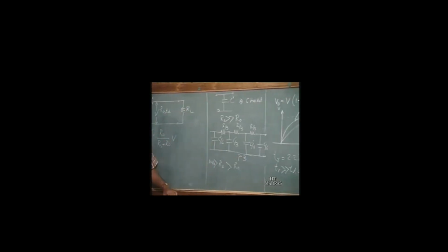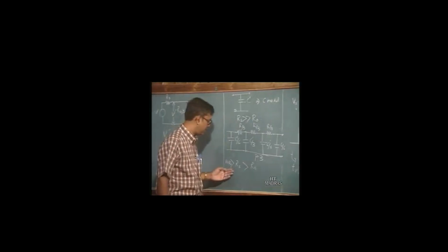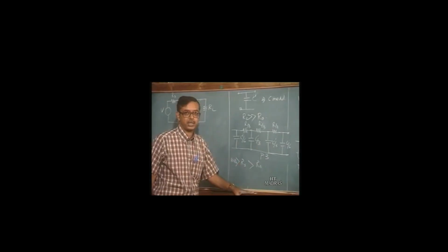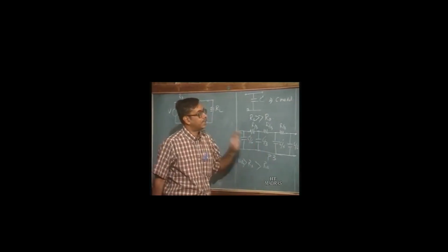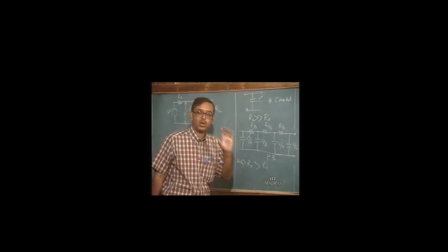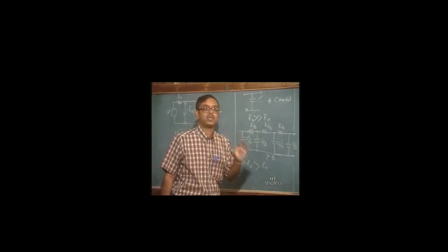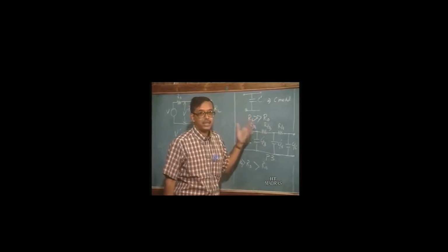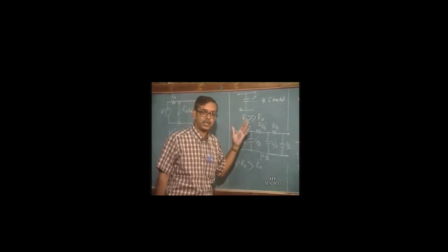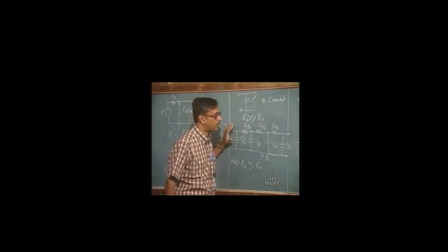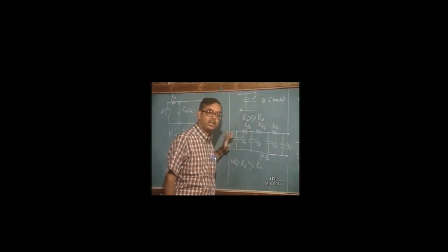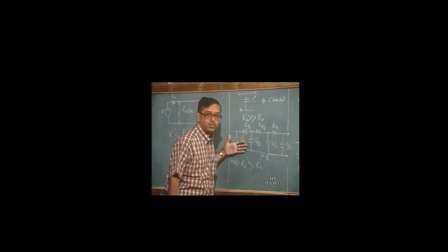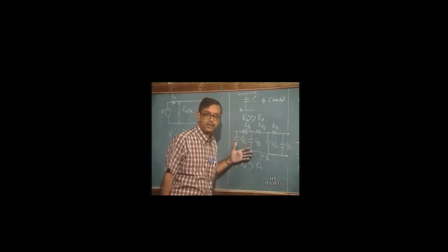When the source resistance becomes less than the characteristic resistance, we have to go for transmission line analysis. In fact, we must remember that the transmission line analysis is always correct. It always gives the best results, but in many cases it may not be necessary to go into the transmission line analysis. We can use these simple models to get results which are similar to the transmission line results and with much less computation time. So that is the advantage.